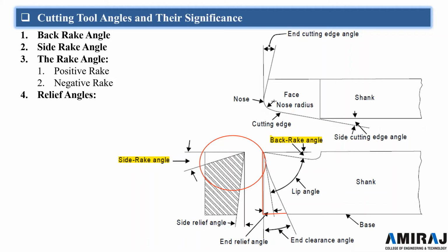So relief angles are for the purpose of helping to eliminate tool breakage and to increase the tool life. If the relief angle is too large, then the cutting tool may chip or break. If the angle is too small, the tool will rub against the workpiece and generate excessive heat, and this will in turn cause premature dulling of the cutting tool. Small relief angles are essential when machining hard and strong material, and they should be increased for weaker and soft material. A smaller angle should be used for interrupted cuts or heavy feeds, and a large angle for semi-finish and finished cuts.